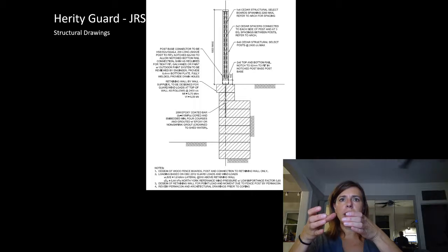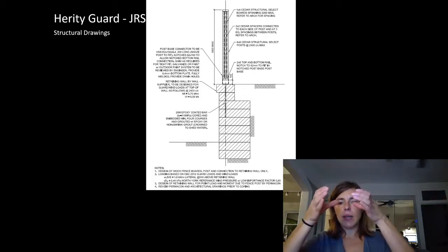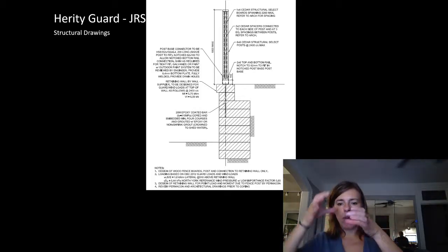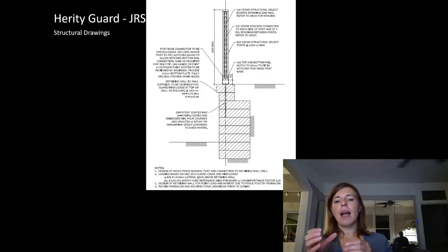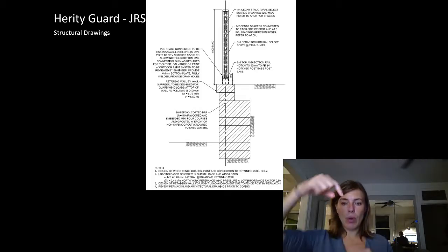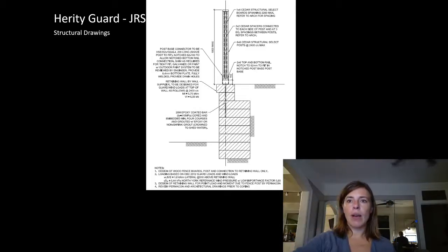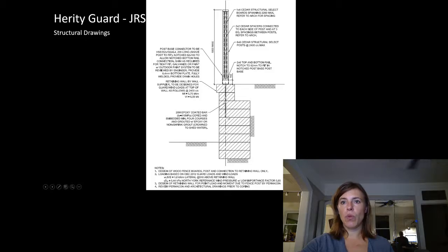I think it was a 6x6 that we ended up with. Yeah, 6x6 that they shaved down to get fit tight into that shoe. And then that had an anchor welded to the bottom of it that was cored down into the Armorstone. So 4 layers down into the Armorstone.